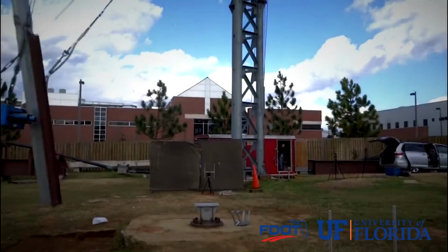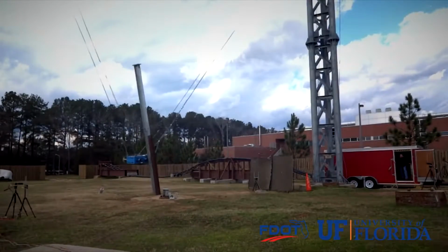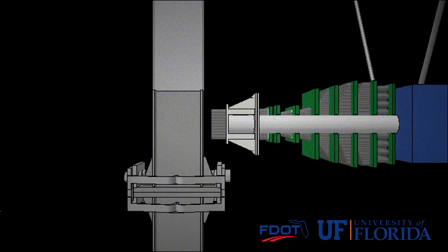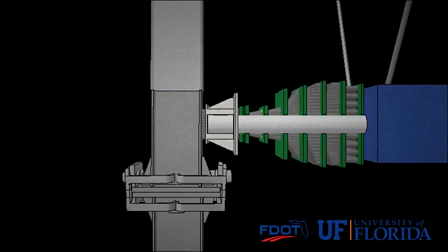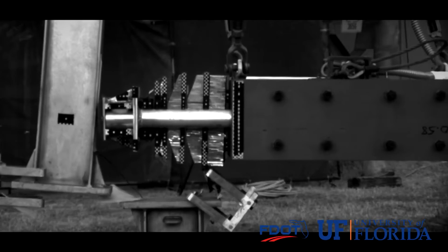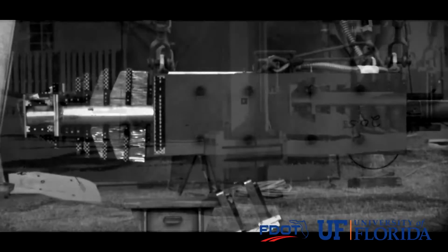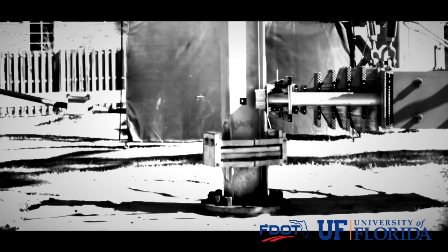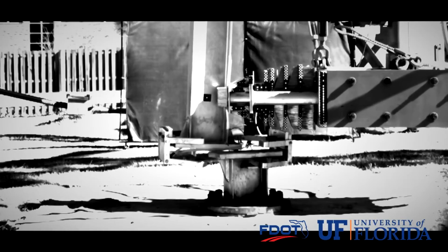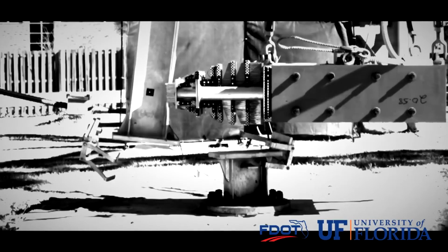Due to cable interference, a full 3-post system was not able to be tested with the pendulum. Therefore, a comparable single-post test was designed and conducted. The physical tests were compared to single-post FEA impact simulations and confirmed that the FEA adequately predicted the behavior of the breakaway components. The data processed from the accelerometers placed on the crushable nose demonstrated great results far below the maximum occupant risk limit set forth by AASHTO-MASH.